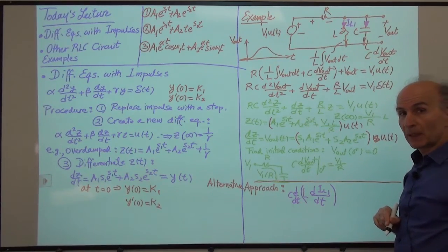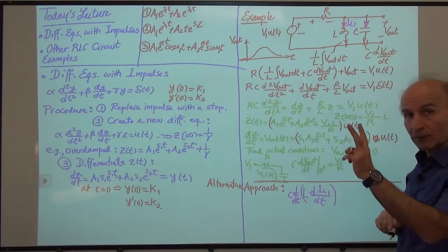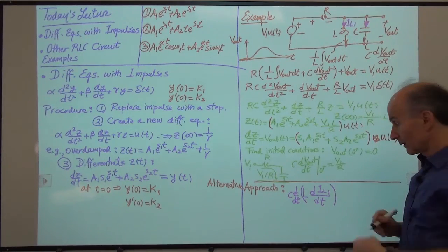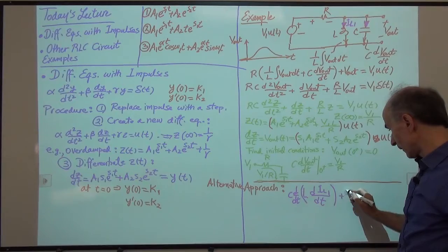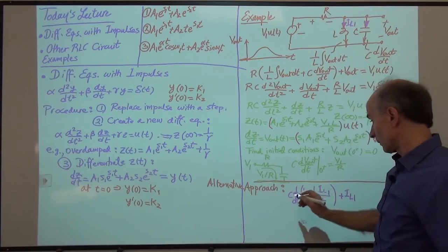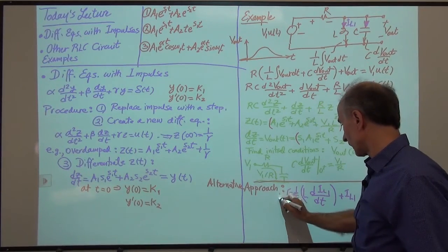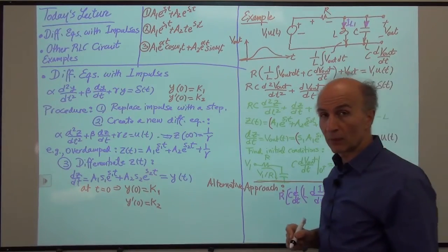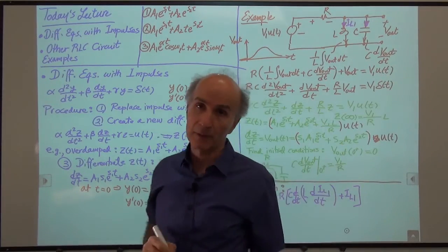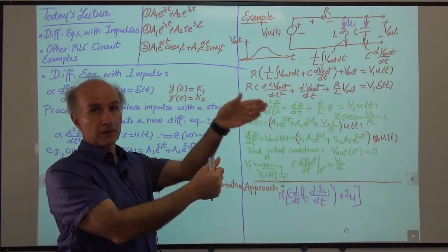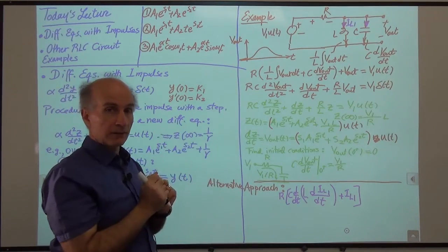Now, the two currents through the inductor and the capacitor add up and flow through the resistor. So that plus IL1, this plus this, flow through R. So multiply that by R. This is the voltage across the resistor. I added the two currents, I let the result flow through the resistor, and I generate a voltage.